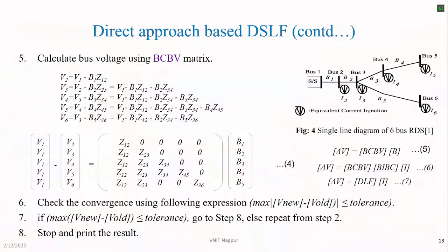Thereafter we have calculated whatever the voltage at node 4, and this node voltage 4 is supposed to be whatever the node voltage at V3 minus whatever the drop across this line, Z of 3 to 4, which we can calculate.